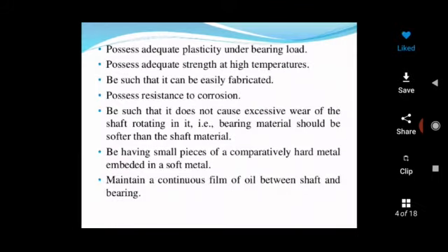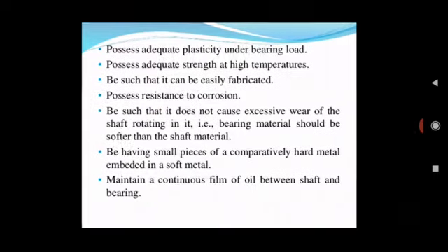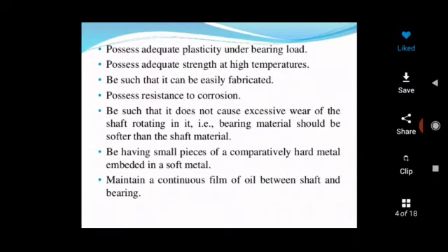There are some other properties also which are required for the bearing material to possess. These include plastic deformation. It should possess adequate plasticity. That means it should be able to plastically deform and should not be brittle, otherwise it is going to break. Similarly, we require adequate strength at high temperature.